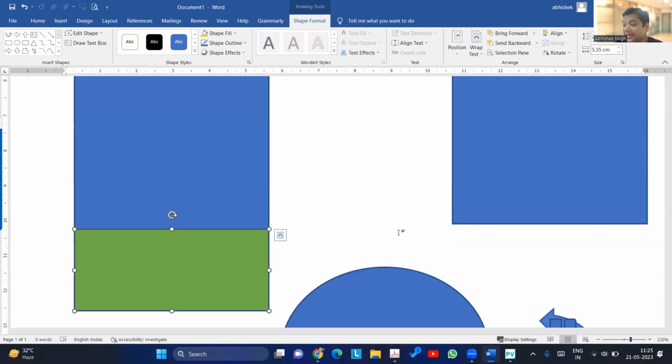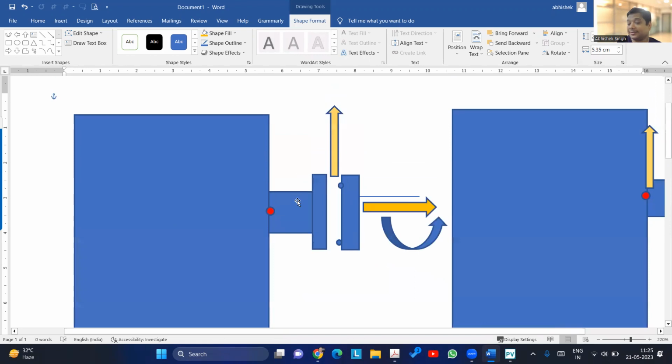So we need to add that calculation. PV Elite does not perform the nozzle neck check for the external load. So remember that. Always you have to add this. Many times we forget. Even an AI may not be questioning that, because they don't see that regularly.